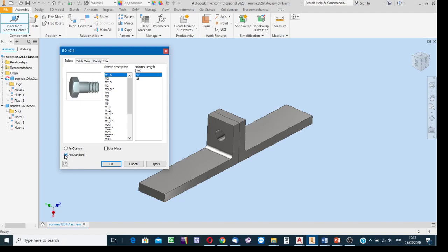If you select the as standard option, then it is going to be defined as standard, and thereafter, after having it as a model in the environment, when you attempt to modify it, for instance, cut a certain part of the object, then you receive an error message. The system will say that it is a standard component, you cannot edit it.